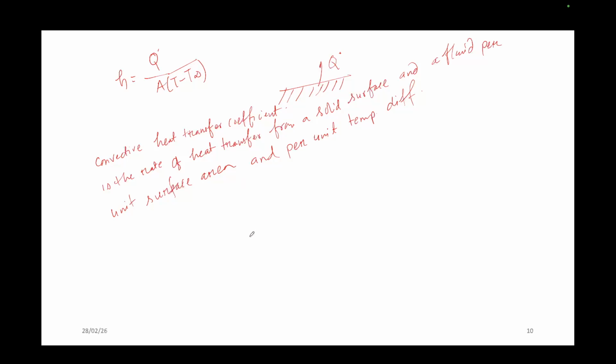Generally, as you have studied in fluid mechanics, if this is a solid surface and the fluid is moving here, you observe that just on the surface the fluid motion of this particle is almost zero, right? So we can say that this fluid particle is not moving, though the fluid has a certain velocity. Such a condition is known as the no slip condition.